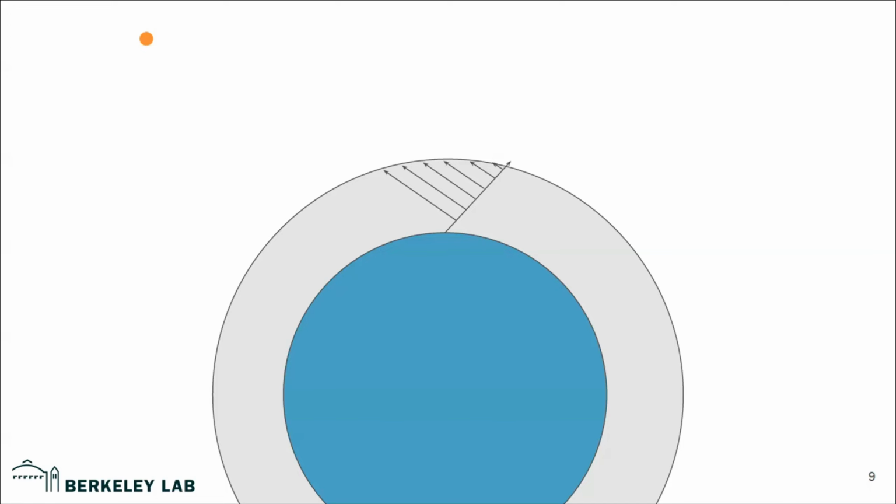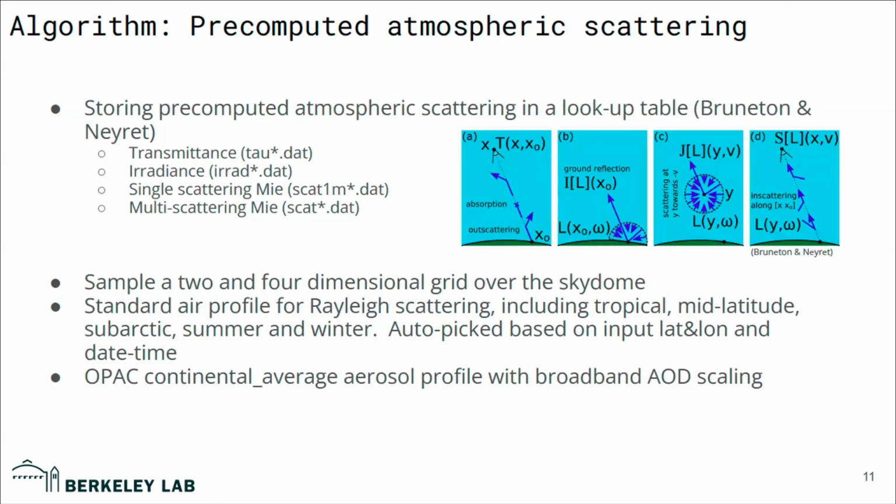But single scattering is really not enough, so we have to do multiple scattering. This is when we have to consider the in-scattering from a lot of positions across the atmosphere layer. For every single one of these incident directions, we do another numerical integration that sends a bunch of rays to the sun again, and integrates along those paths. As you can see, those computations can become very intensive. The overall algorithm that we implemented is based on the Bruneton and Neyret algorithm published in 2008.